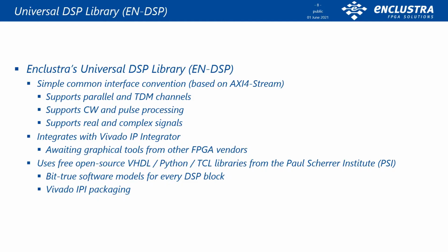I think the key to finding something that worked well for us was that one of our engineers was able to design an interface convention that is simple enough to be easy to use, but still general enough to cover the vast majority of use cases. This means each block can support parallel and TDM channels, continuous wave and pulse processing, and real or complex signals.